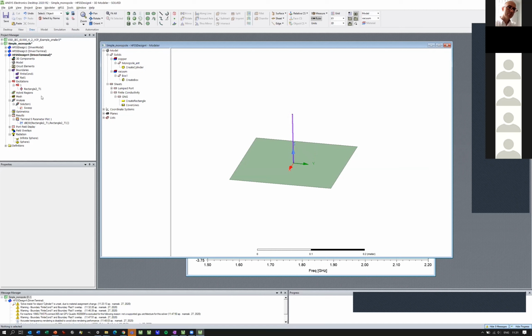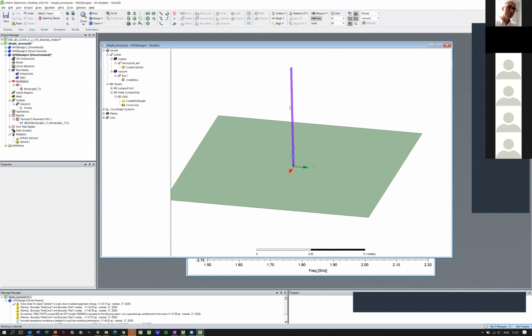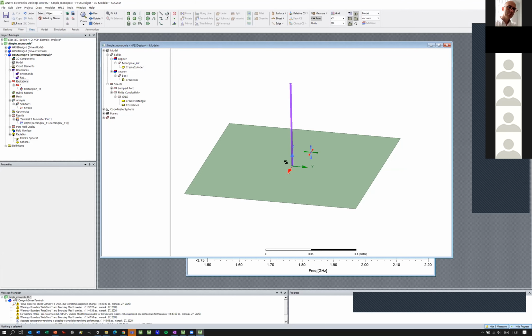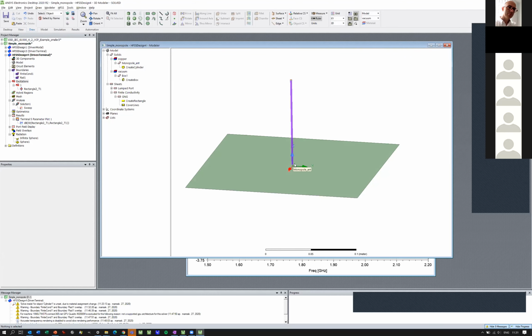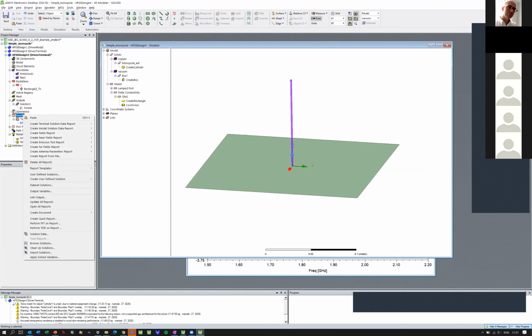And by the way, this is my antenna port. If I go to my excitation, it's 50 ohm, as this is a default. It's a 50 ohm excitation port. I don't know if my antenna is really tuned for 50 ohm. It's maybe not. I can get more results by right clicking on the results, and this was the one we just created, the rectangular plot.